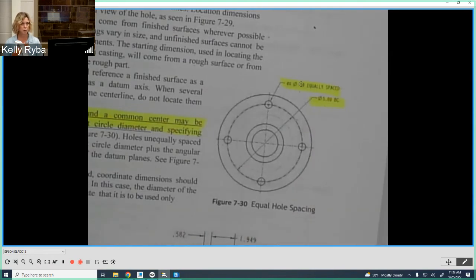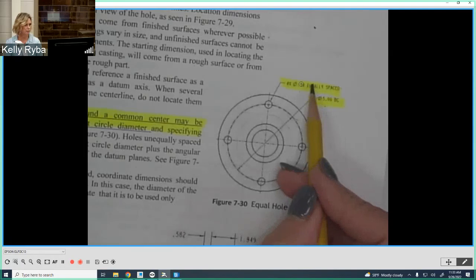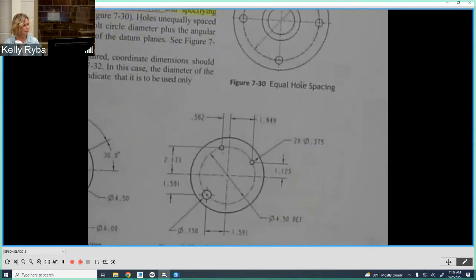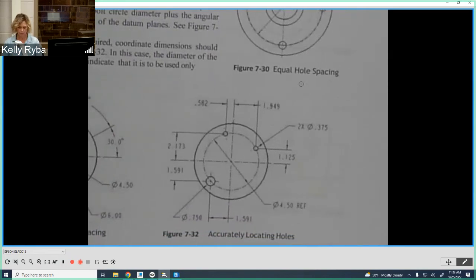I believe Creo will default by dimensioning it 2 separate. And sometimes you just don't have the room, so you might have to combine, and that's okay. Another way that you can dimension holes, and it's completely legal, is to do it from the center line. Sometimes you have different holes in different locations and they don't really line up with equally spaced or at a certain angle or whatever it might be.